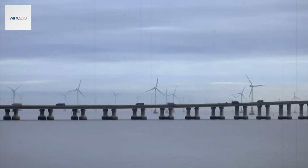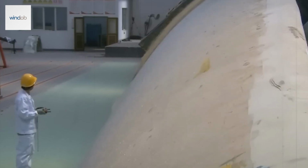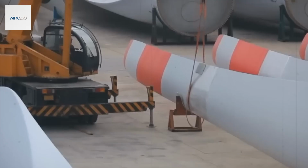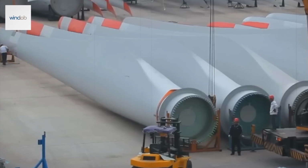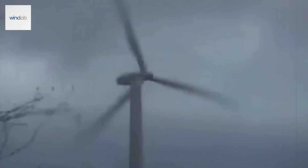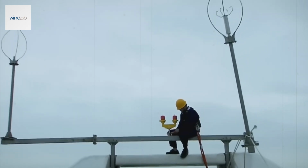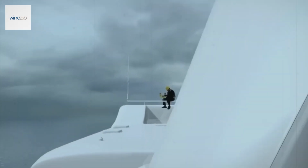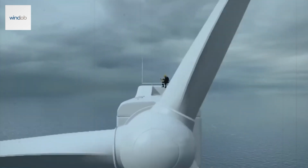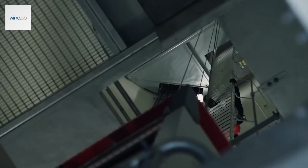It all commences with the rotor, which is composed of 3 long aerodynamic blades that are connected to a central hub. The turbine is spun by the blades, which are meticulously designed to capture the wind. The rotation is subsequently transferred to the main shaft, which extends into the nacelle, the substantial structure that sits atop the tower and houses the system's heart. The blade's sluggish rotational motion must be significantly enhanced within the nacelle. That's where the gearbox comes in.